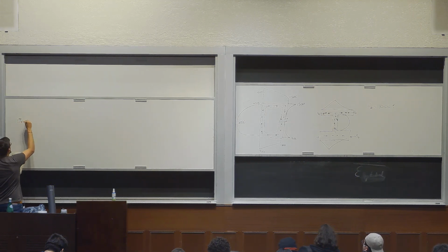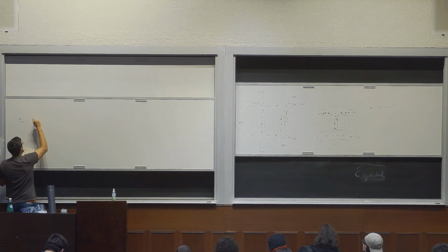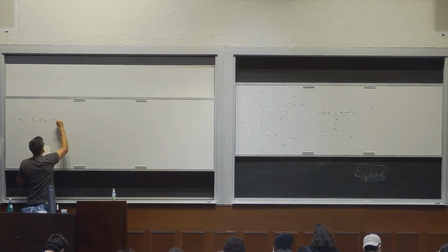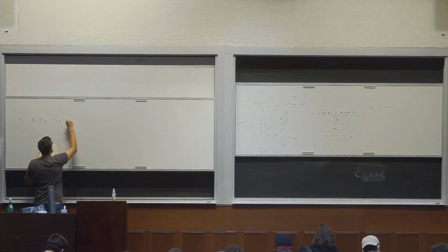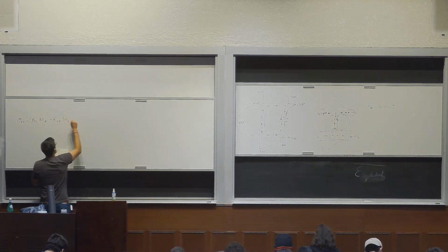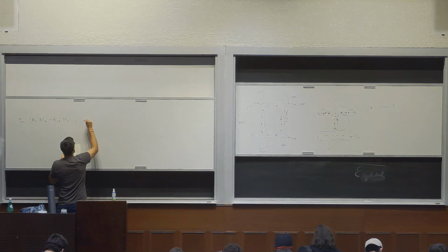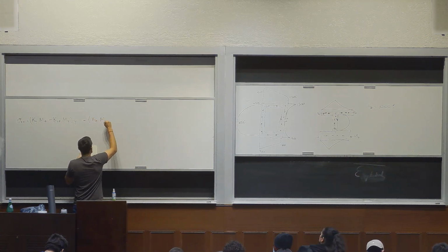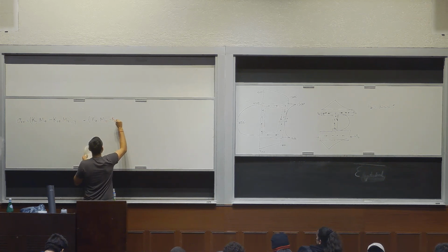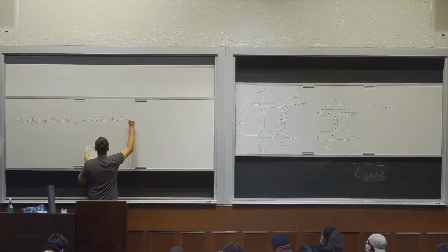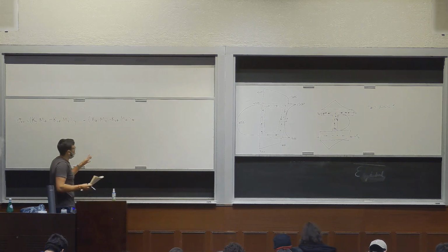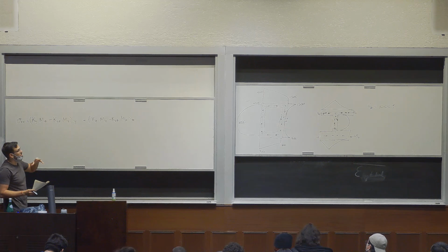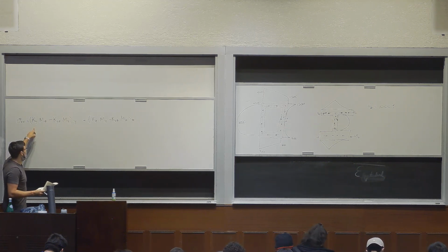So sigma xx equals (ky Mz minus kyz My) times the y position, plus (kz My minus kyz Mz) times the z position. So that's the same equation that you guys had seen previously, except we've replaced a lot of these moments of inertia terms with these k's.